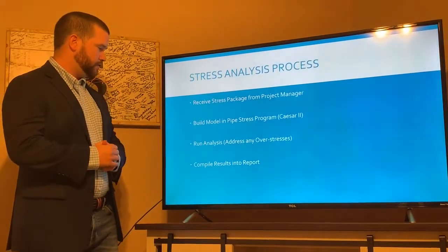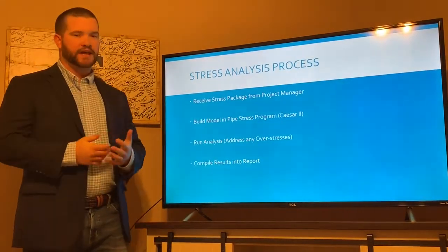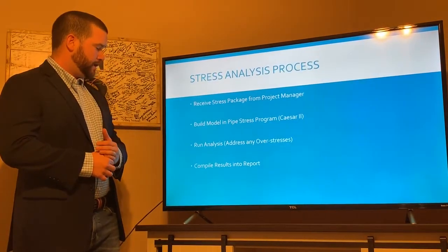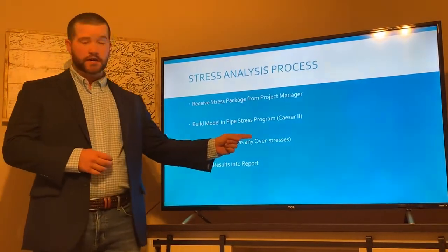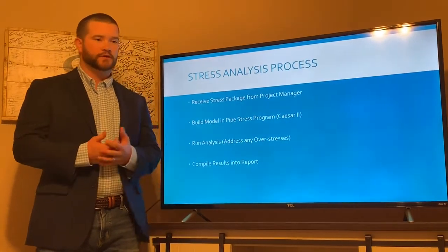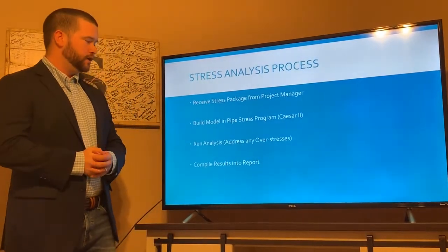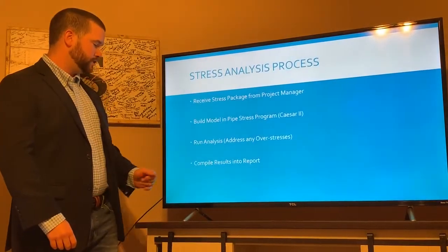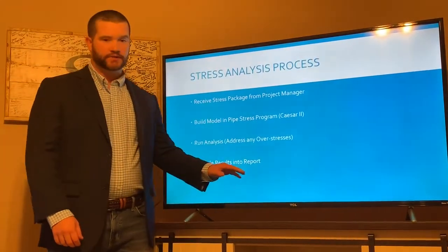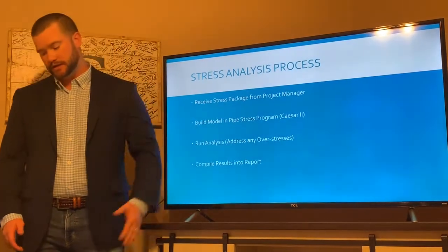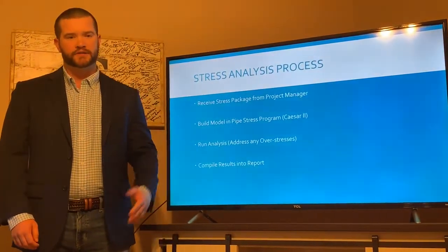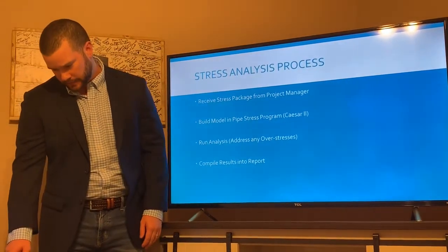It runs computer modeling almost like an FEA to analyze every piece of the pipe. After you run it, you're going to address any overstress areas. If there's any failures due to stress, you're going to analyze the results and see how you can fix any issues. And then you're going to compile your results into a report that can be submitted to the project engineers and the pipe designers and civil engineers and structural guys.